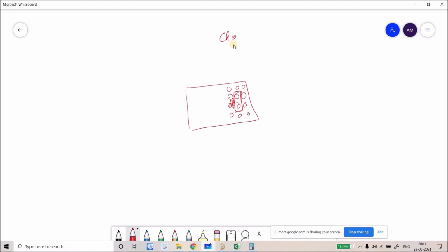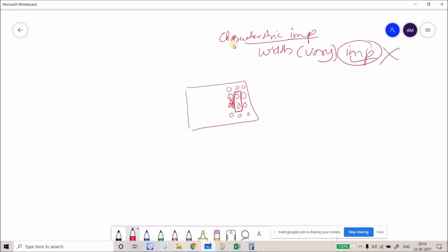It should follow the characteristic impedance, right? And that means the width of the track. If the width of the track varies, the impedance of the track will change. You're getting it? The impedance will be wrong. Because of that impedance discontinuity, we use that term here, there will be a lot of SI problems, right?